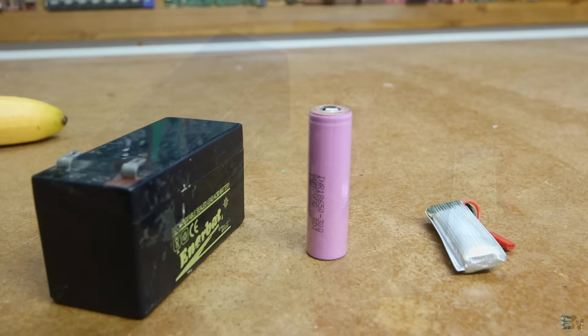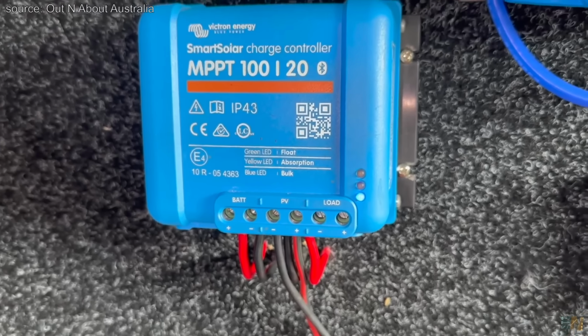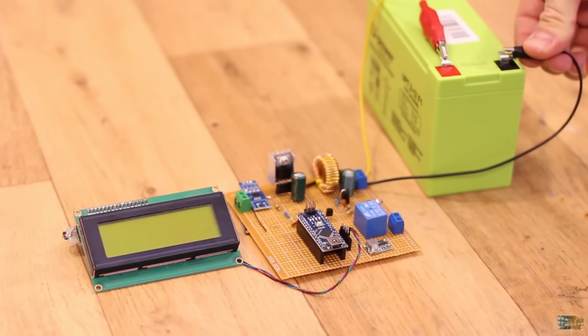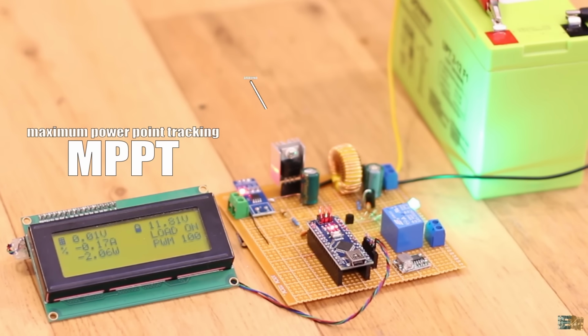Oh, and another thing that we made in that MPPT project is that usually these kinds of devices have preset points. So you can select what type of battery you are charging. If it's a lead acid battery, a LiPo or a Li-ion battery, you can select that in the menu, and it will have some pre-adjusted points, so it will know from what voltage to use a PWM signal and just make a constant current value, and then it will know from what voltage up to the maximum voltage to use MPPT, and so on. So usually they have preset values, and that's what I made in my tutorial.